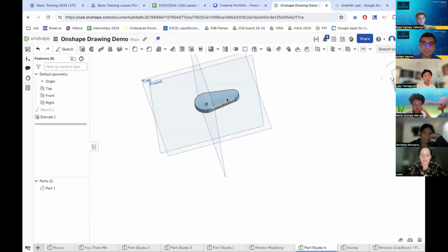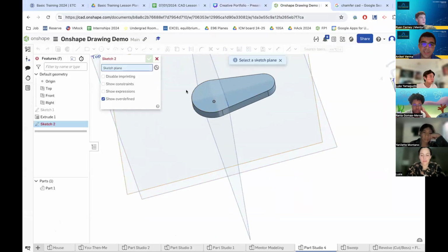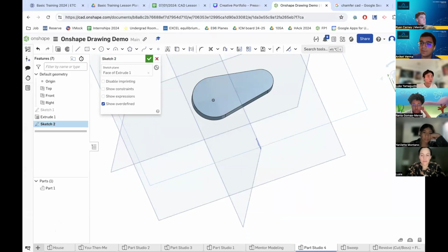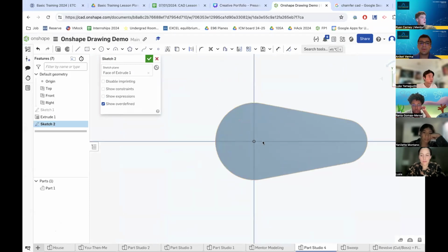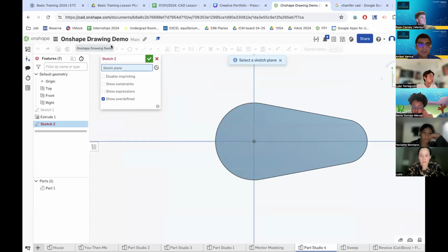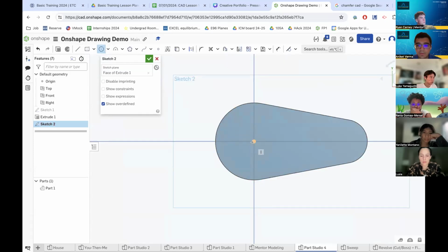Okay. That said, we're going to start a sketch on the top part of this part over here, and we're going to draw the inner circle. What the heck? Where did that circle come from? We're going to draw the inner circle starting at the origin, because that is the center of our previous circle. So we are chilling. Boom. And if I'm not wrong, the diameter of this circle was 20 millimeters. So we have a fully defined inner circle over here, right?